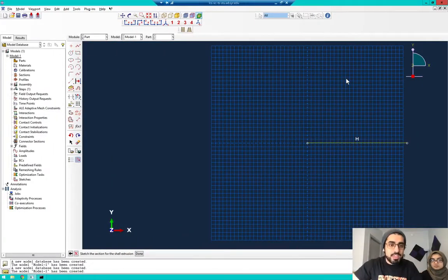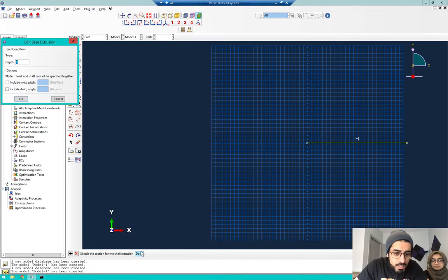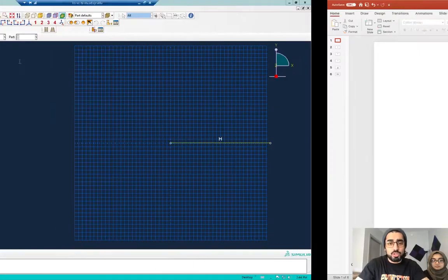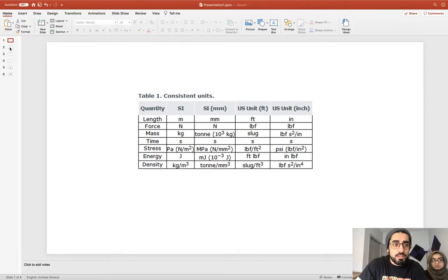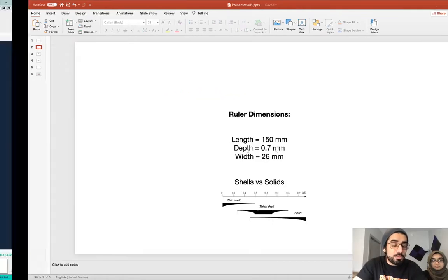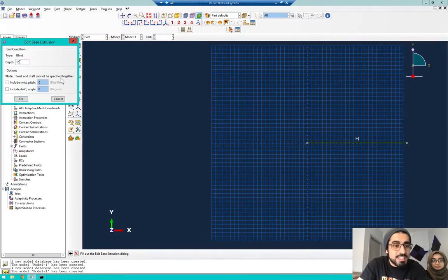You just draw the thing and you assign a thickness to it. When I'm done drawing this thing, that's it. Okay, I click done. And they ask me how much depth I want, how much I want to extrude it. What's the extrusion depth? From here, it's 150 centimeter, or rather 150 millimeter. I cannot put 15 and say centimeter. No, it doesn't work. I need to put what?